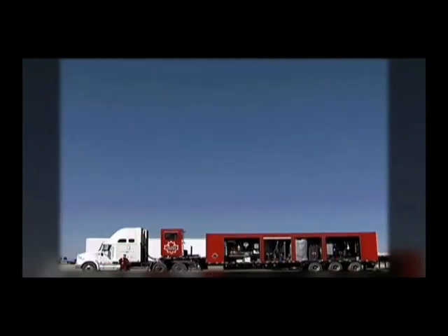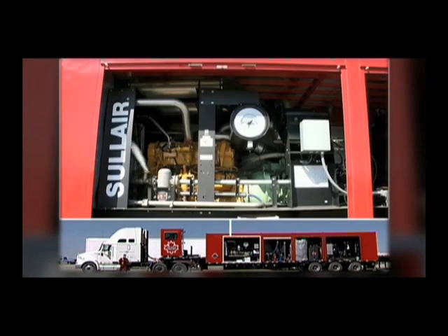The process for creating nitrogen begins at the front of the trailer-mounted unit. Ambient air is taken in through the intake filter and builds pressure in the oil separator, reaching 40 to 60 psig. When the system is loaded, engine speed increases to 1800 to 2050 rpm, and the control system loads the compressor, building pressure to 350 psig. At this point, the compressor delivers air to the membrane pretreatment system.